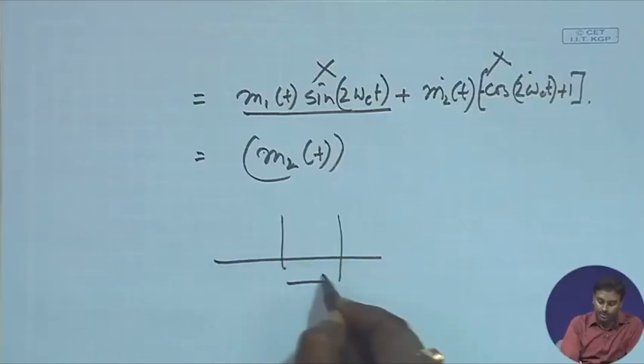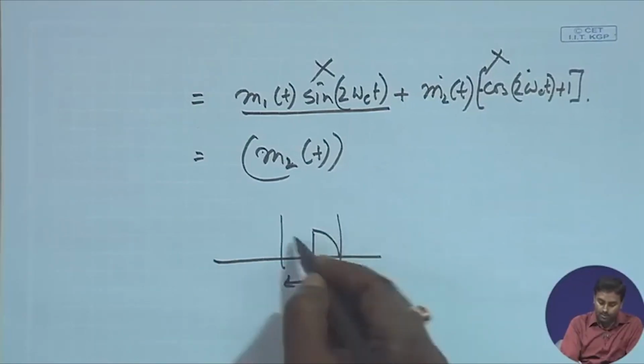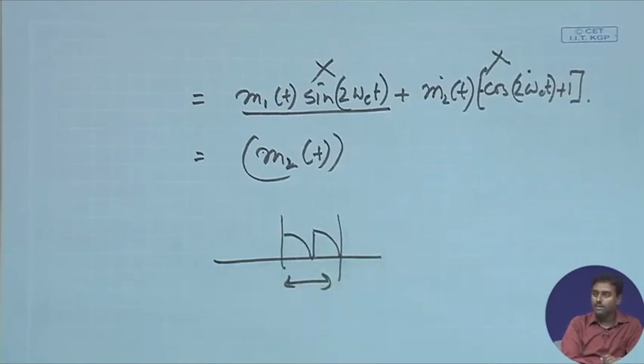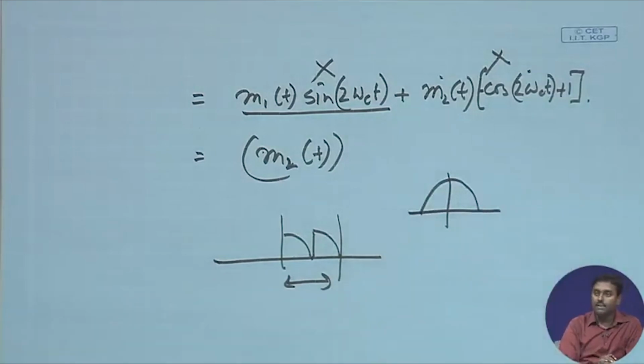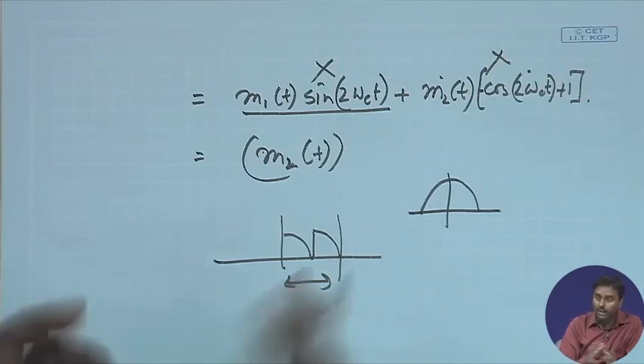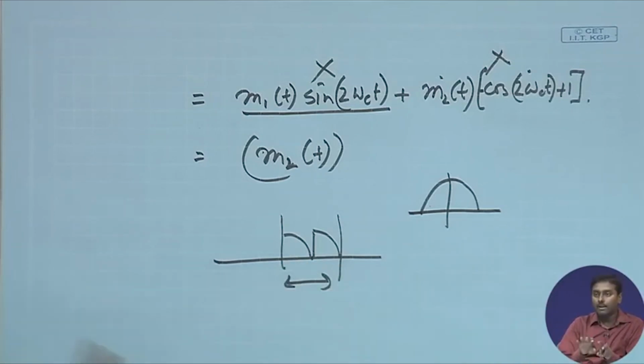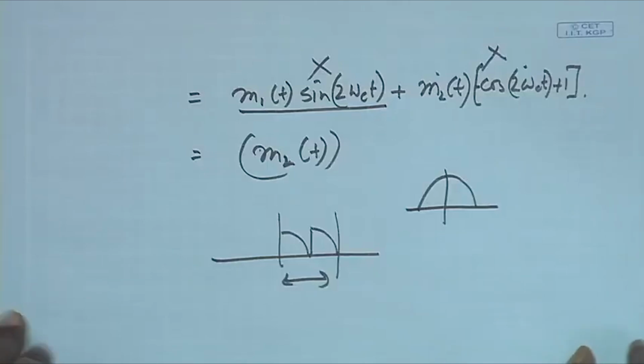It is almost similar, means bandwidth efficient as SSB signal, because in SSB also if I had this 2B band, I was putting 2 SSB signals, whereas here I am occupying a composite signal and it has both of them, right. So, m1(t) as well as m2(t), and I now know that I can demodulate back both of them. So, equivalently I am able to transmit a similarly bandwidth efficient modulated signal as SSB.